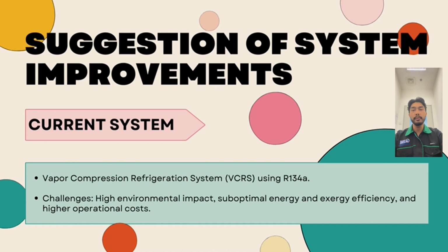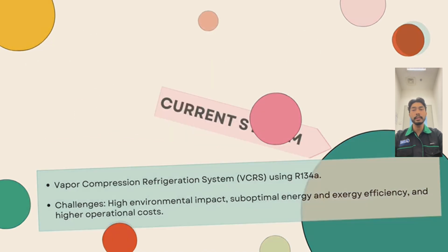We evaluated different evaporation and condensation temperatures and copper tube diameters for both the refrigerant and water sides, considering total equivalent warming impact, coefficient of performance, exergy efficiency and total plant cost rate. The optimal conditions: we found the best performance at an evaporation temperature of -3 degrees Celsius and a condensation temperature of 45 degrees Celsius, improving all metrics.